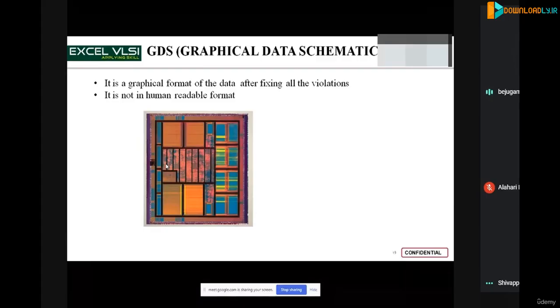One query arose: what is tape out and sign off? Sign off is where you are performing checks, like the timing issues, the DRC issues and the physical verification issues. That is called the sign off stage. And the tape out stage is where your complete design is sent to the fabrication industry for manufacturing. So the testing stage comes under sign off, and giving the complete implemented circuitry to a manufacturer is called tape out. So this is the complete flow of ASIC.